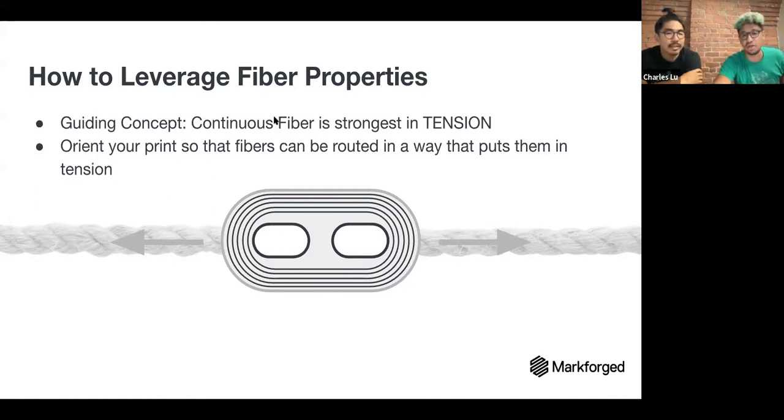You can imagine a point load coming on the exterior wall of this part. Although that would be a compressive force, it is locally putting those fibers in tension, which is why you'd want concentric rings. This was really counterintuitive to me at first. Because any sort of load that you place onto a part can in a lot of ways be translated to another load.